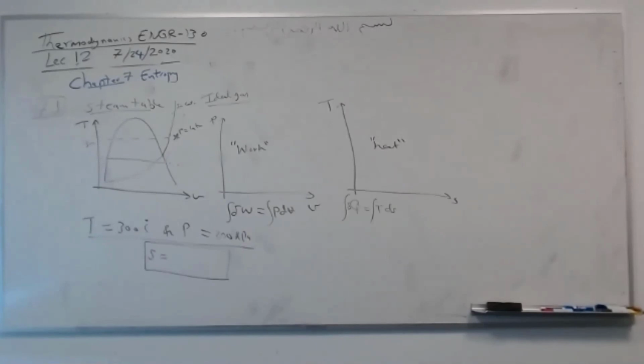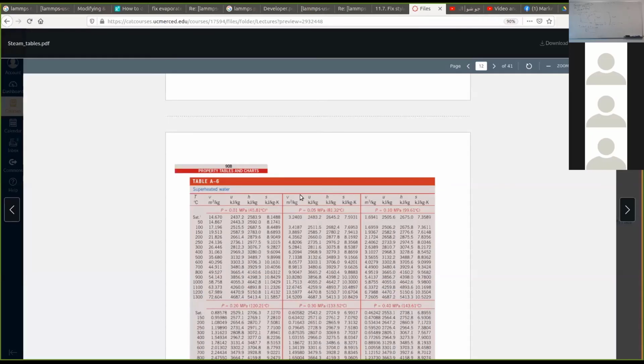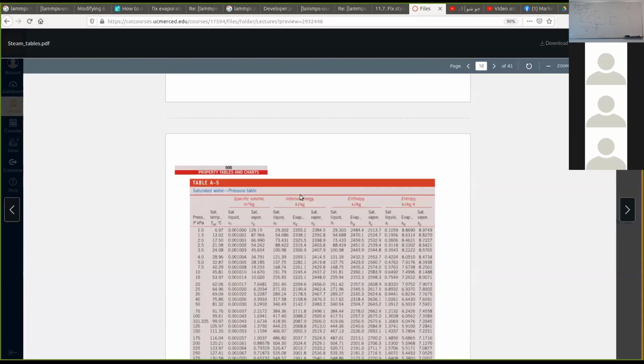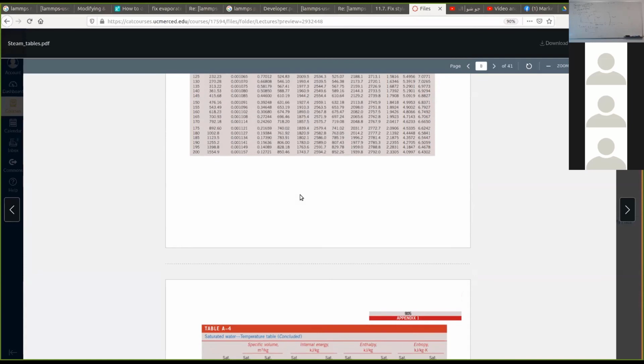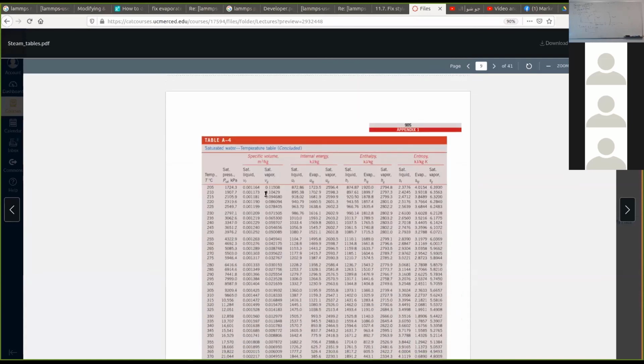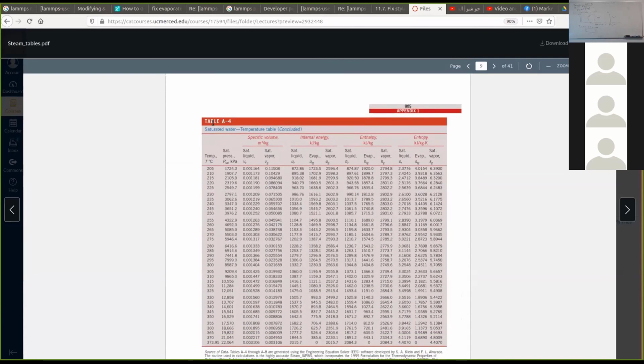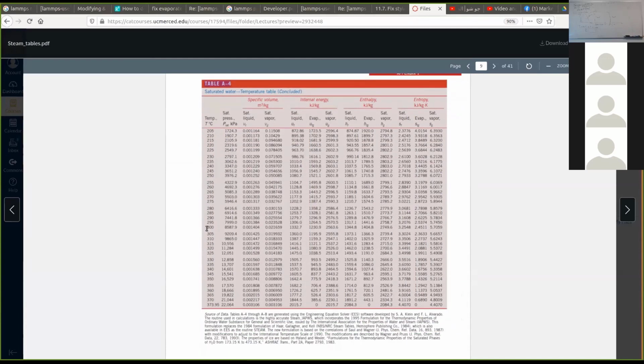Let me share with you now, for example, the steam table. First of all, you start with table A4 because temperature is given. Temperature was 300 Kelvin. This is table A4 for water, but table A11, 12, 13 for refrigerant 134A. So it's water here, temperature 300.